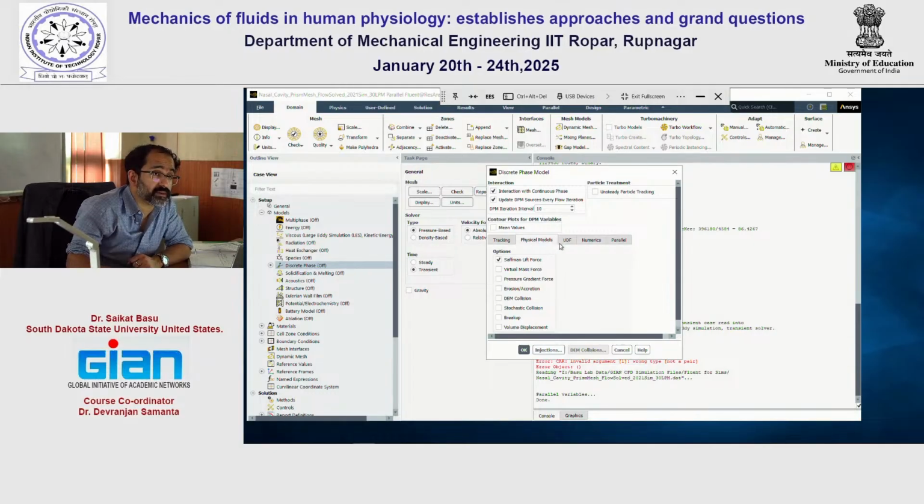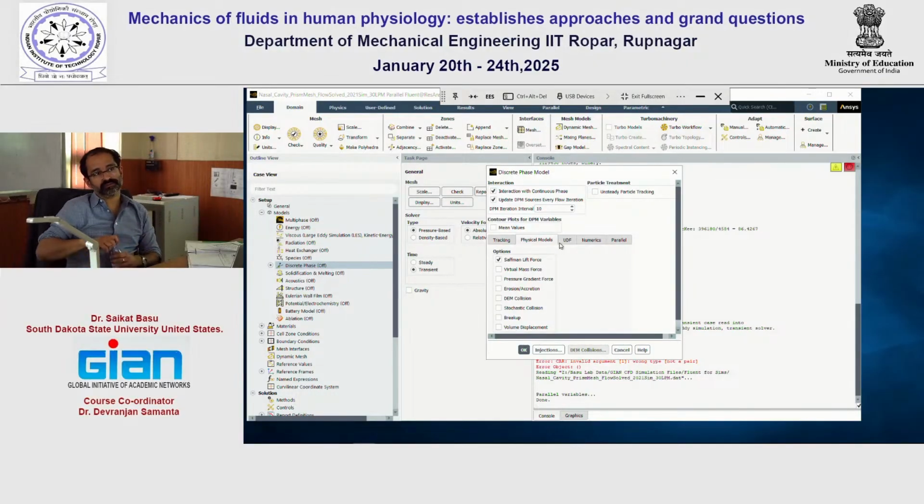Actually, I read this assessment. This is generally connected to the slip velocity, like the particle with respect to the flow. It is connected to the slip correction, right? Basically, when you have the small particulates, that Cc correction that we are doing is connected to that. So when you have very small particulates moving cross stream, now the question is, what do you define as small in this context?